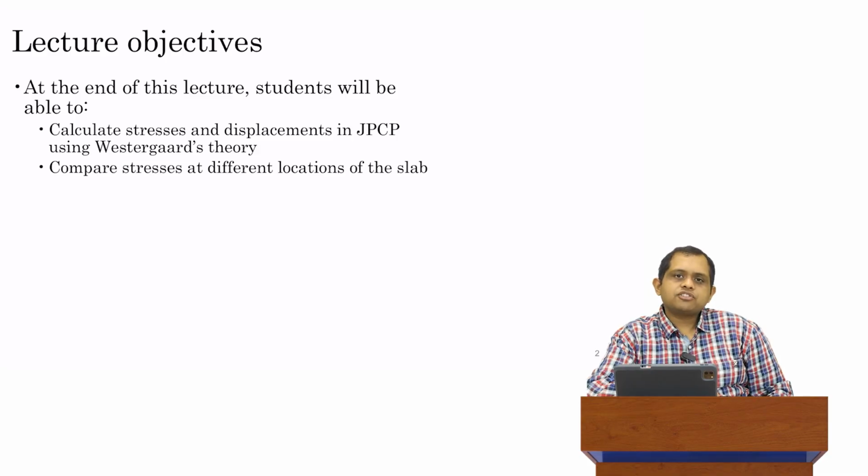So in the previous lecture, which was lecture 5, I introduced you to plate theory. I explained that you could use layered elastic analysis to analyze flexible pavements. Now, LEA is used to analyze flexible pavements, and one of the basic assumptions in LEA is that in the horizontal direction, the slab or the structure is of an infinite dimension relative to the thicknesses. Mathematically, R tends to infinity, where R is in the horizontal direction.